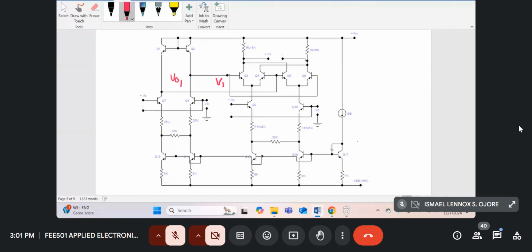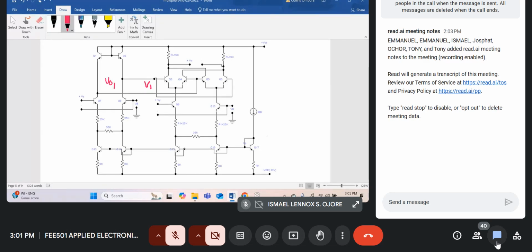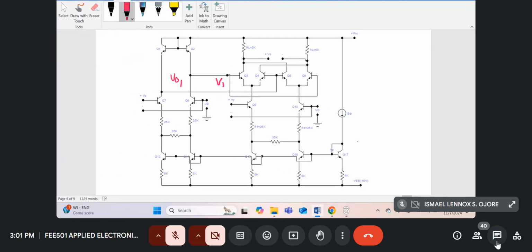It makes the signal that goes to V1, which is our normal Gilbert multiplier cell, be such that we can extend the dynamic range of our Gilbert multiplier cell. And it does so by distorting the signal with a tan hyperbolic inverse function, which we shall see later on.